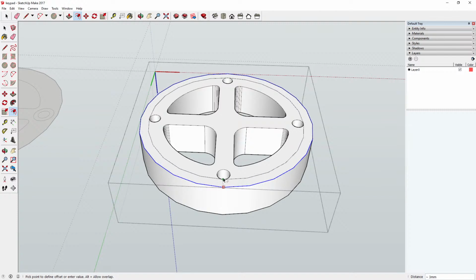Yeah, so we've got to keep it where we can mill it. The edge, it'll be snapped off if it's too thin. Although, well, we're milling out in circle, so it can't be too thick. It's got to overlap, so thickness doesn't need to be too much. It's 2 mil, 2.5 mil. Let's say 2.5 mil.